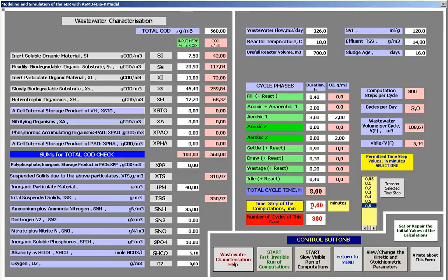As we put here, as you see, we put the mouse over this, this appears, we select this number, and transfer the time step to the database. And then we will have to select the number of cycles that the program will perform. Usually we put a big number, and the calculations will stop converging in a lower number of cycles.